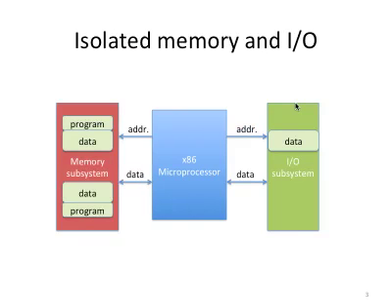But the good thing for isolated memory and I/O is that because they are in separate memory spaces, you use different instructions for accessing content from memory or I/O. So you have specialized I/O instructions.